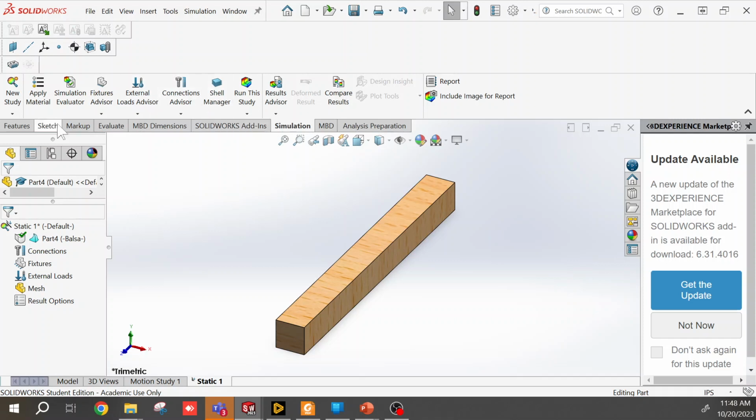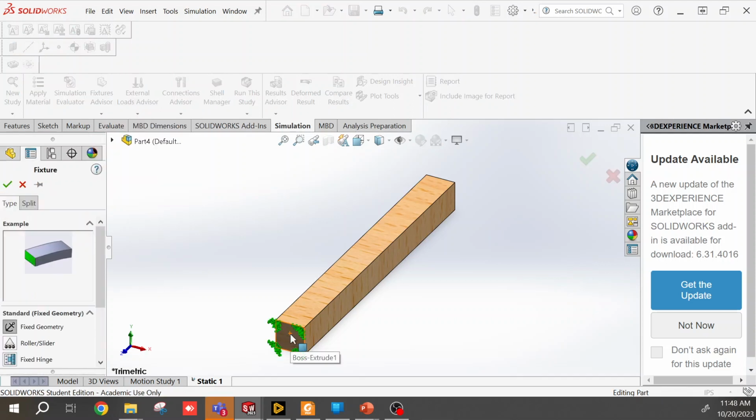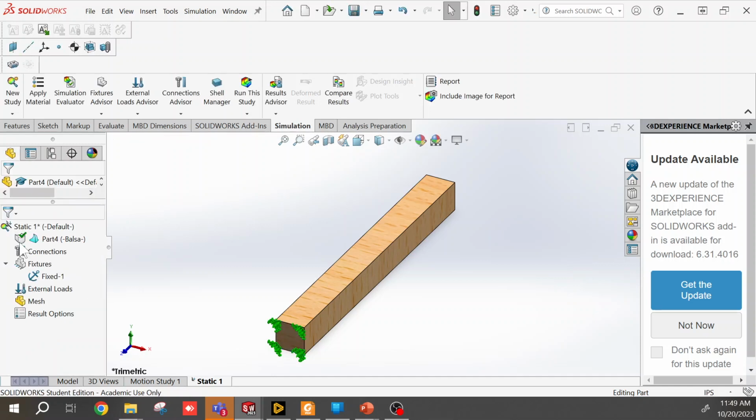We were told in the PowerPoint that we wanted to apply a load and a constraint. So luckily, a lot of the process flow is left to right in SolidWorks here. So what we want to do is, under fixtures, apply a fixed geometry to one side of this balsa diving board that's oddly shaped. So I will apply a fixed geometry here. And on the other end, you click the face that you want the fixed geometry to be.